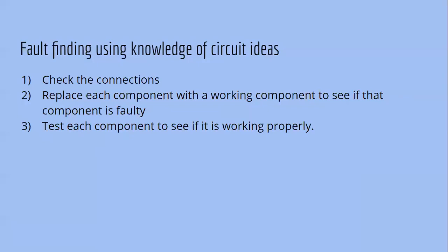So first you just use the wires in another circuit and see if that properly working circuit is still working or not. If it is working, then that means there's no fault with the wires, right? Now you take the bulb from the faulty circuit and you use that in the working circuit. And if that bulb isn't working, then that means that probably the bulb is faulty.